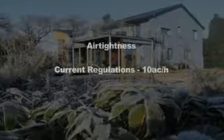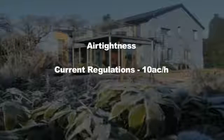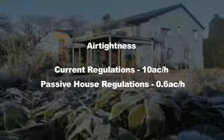And in terms of airtightness, the current building regulations require an airtightness of about 10 air changes per hour, whereas the Passive House standard requires an airtightness of 0.6 air changes per hour. So that's what we'll be covering in this next series.